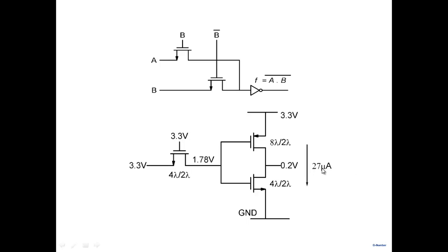So the solution to that may be, can I have two different transistors in my process? A transistor with threshold voltages of +1 and -1, and maybe a transistor with a threshold voltage of 0. All right? A 0 here. If the threshold voltage was 0, then 3.3 would pass very nicely here. Or a very low VT. Suppose I had a pass transistor with a VT of 0.2 volt. So for 3.3, I will get something like 3 volts here, and 3 volts here would nicely get restored to 0.